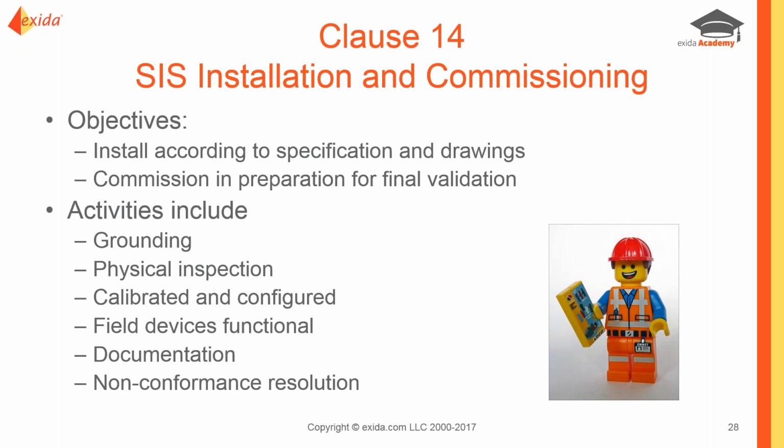So the plan needs to define what's expected in terms of the plan or the procedure, depending on how you approach it. Your construction management plan certainly needs to look at all of the testing going into the commissioning, because there will be basic construction testing that should be done by the contractors or the construction team. But then there's also the acceptance testing that the owner and operator team is going to want to look at, such as double-checking the grounding and the calibration. Bench calibration is good. Field calibration is what we want to accept on.